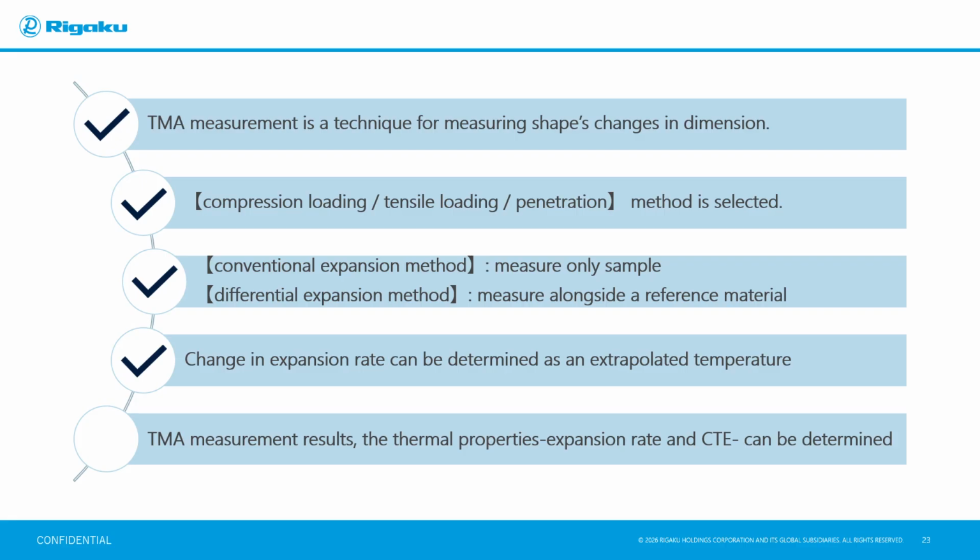When a volume change accompanies a reaction in the sample, the change in expansion rate can be determined as an extrapolated temperature. From TMA measurement results, some physical properties, expansion rate and mean coefficient of thermal expansion, can be determined.